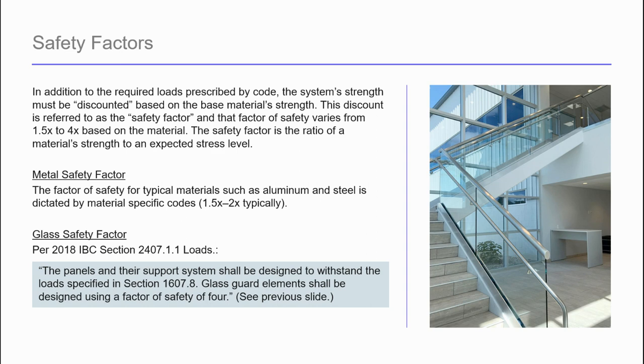This is achieved by requiring the use of laminated glass, and again, we'll talk about that later, and/or tying the glass together with a top cap or handrail, or being able to demonstrate via testing that without a top cap or handrail, the glass has post-breakage structural integrity.